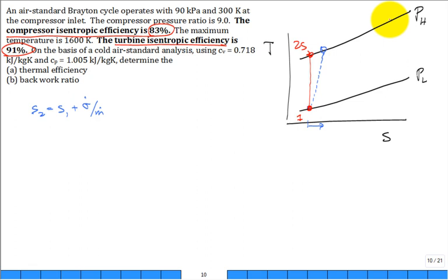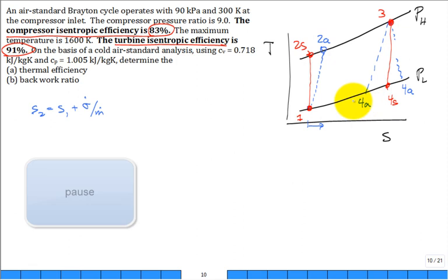All right. We then bring it out of the combustor at state 3. And we used to put it through a perfect turbine down to state 4. But now our turbine is still going to expand the same pressure ratio, so it's going to end up on that bottom line. State 4 is going to be on that bottom line, but it'll either be to the right or to the left. And I know that if I ask this question and I get an honest answer from everybody in the room, it won't be as high a percent correct as the other one. Most of you, I would say 90-some% got the first one correct. Yeah, the 2 actual is over to the right of 2 isentropic. So, which one is it going to be? Is 4 actual to the right or is 4 actual to the left? I'm going to pause, walk around, and collect a few answers.